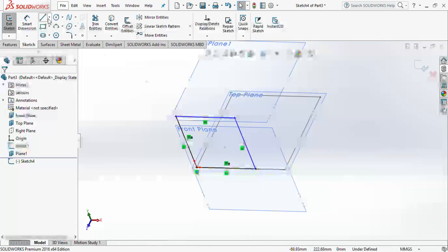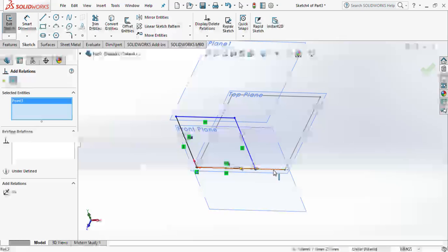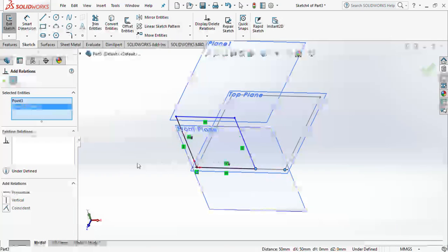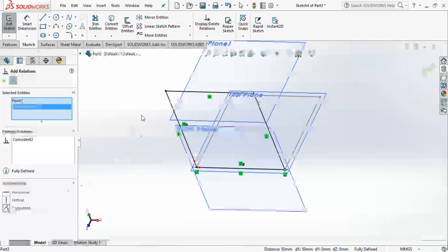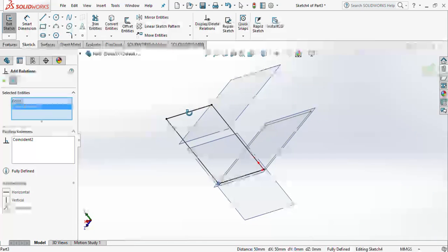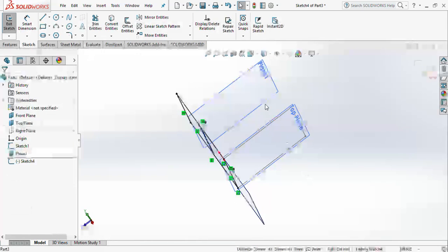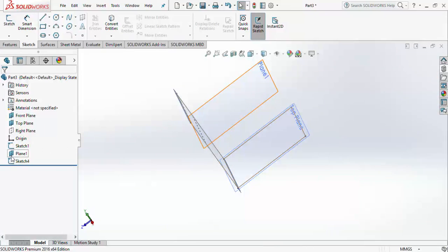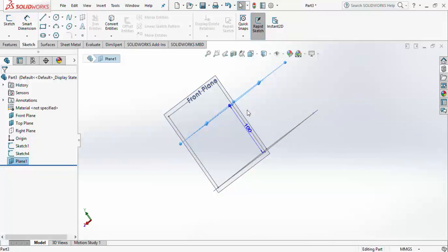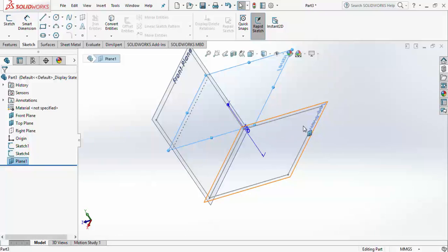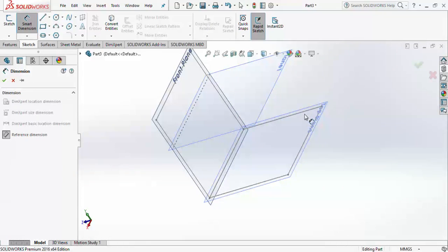Oh, for some reason it's not aligned, but maybe we can constrain these together, coincident, okay, and then we'll have to redraw everything. So I could do this one, get out of that, take this plane downward, just to see where I am. It shows me 100 millimeters, but probably that is not 100 millimeters, which is 150.